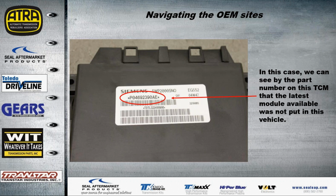Now, just a note, there are many modules that look like this and that will plug in, but they might not function. As a matter of fact, you will be able to program some of them, and they'll take the program and it'll say successfully completed, but they won't work because the module part number is not for that application. So again, that's a very good check to make, especially if you get the vehicle in and somebody had their mitts on it prior to you.